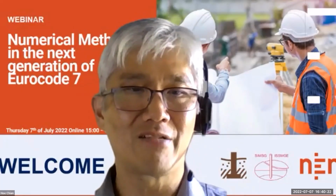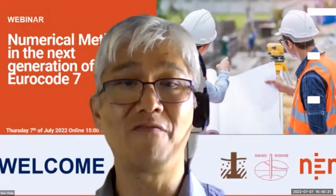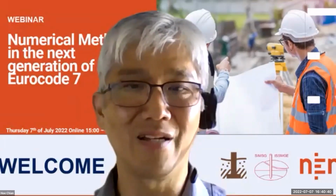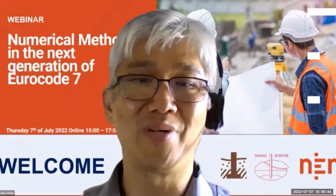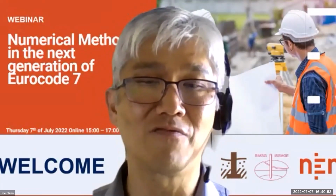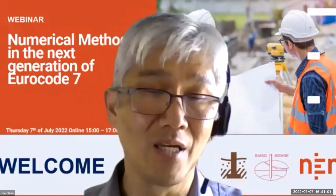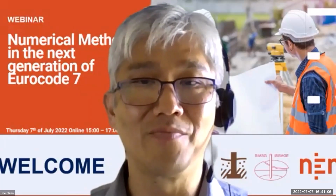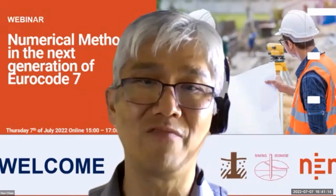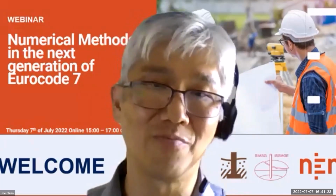And obviously, if you look at the current Eurocode, the characteristic value is the cautious estimate of the soil properties that affect your limit state. If you have experience in the past that your limit state is governed by certain sets of parameters, then that set of parameters is what you need to factor down from. For most of the cases, we call it characteristic, and it's a 95% confidence level. But for some designs, for example, some of the piling design in the UK, all the established design profiles are based on mean value, and then you can take the mean value as your profile, and if you want to factor, you factor from that point.